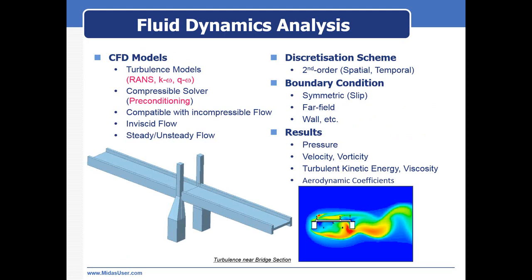Another analysis capability in FEA is fluid dynamic analysis. Let's say I have this bridge model. I model the section in FEA and apply the dynamic wind load. From the CFD analysis, we can get the pressure acting on this section. We can get the vortex formation and we can get the aerodynamic coefficients.